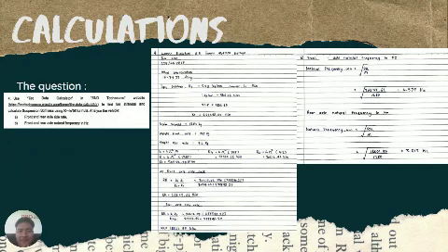Okay, we're going to question number 4. The question is to use the tire data calculator and BND test source website to find tire stiffness, and calculate suspension stiffness using the K equal to 4 pi squared f squared M formula. Analyze the vehicle front and rear axle ride rate and front and rear axle natural frequency in hertz.